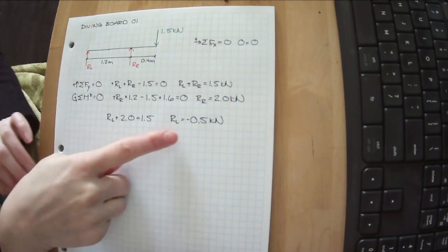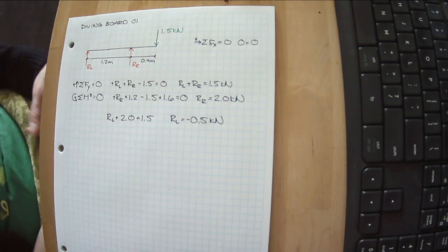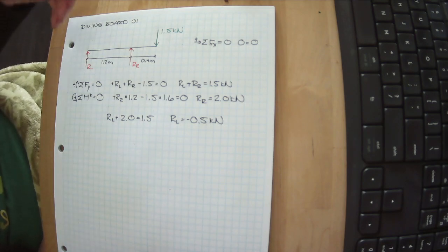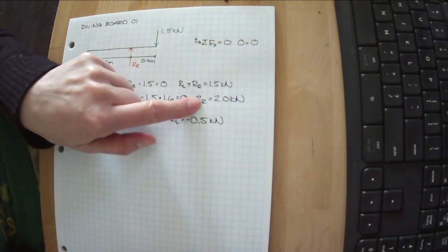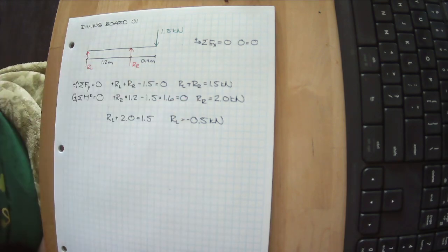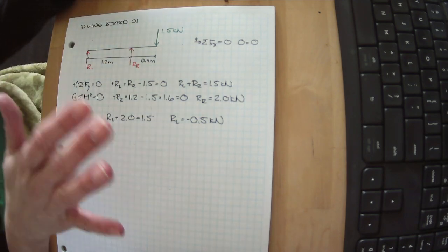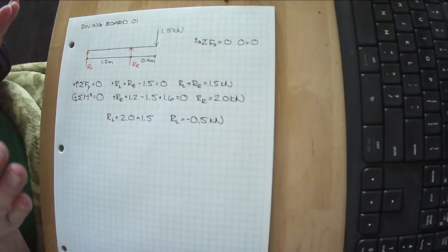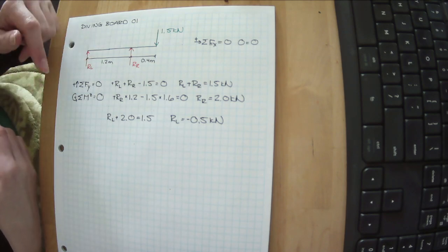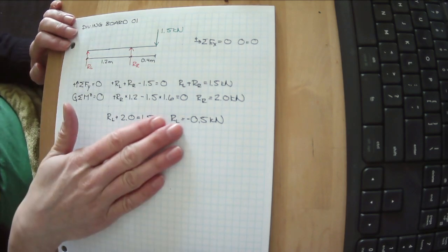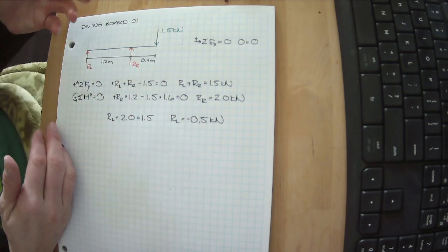That means a negative value telling us we're wrong also happens to always point in the negative direction. If we had done this drawing our arrows downward, our L would have come out positive and our R would have come out negative, meaning we had drawn our R in the wrong way and it should really be upwards. That can start to get confusing. So I will strongly recommend always draw your reactions in the positive directions, and that way a negative answer tells us it's actually going in the negative direction, okay? Or that we've drawn our arrow wrong.